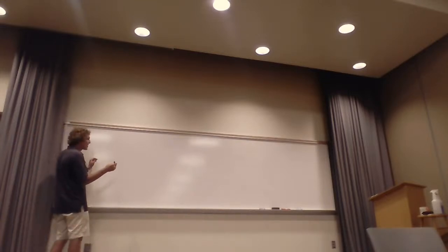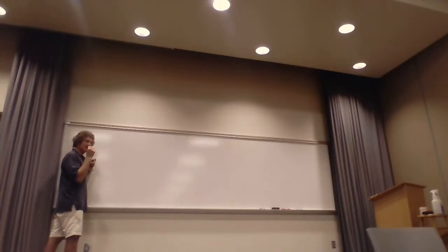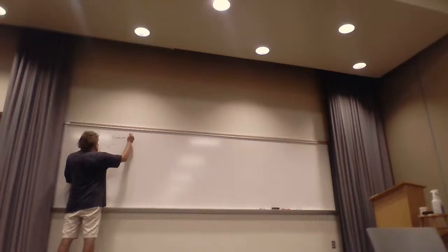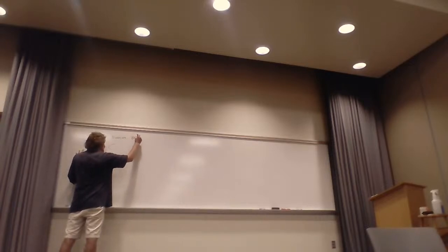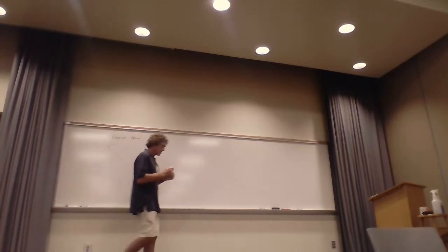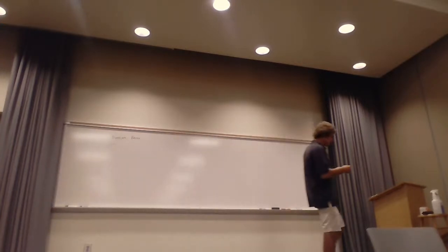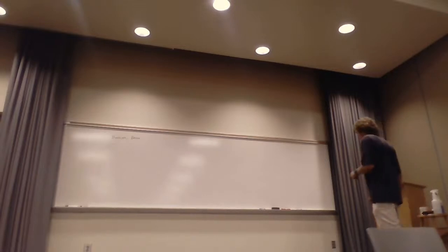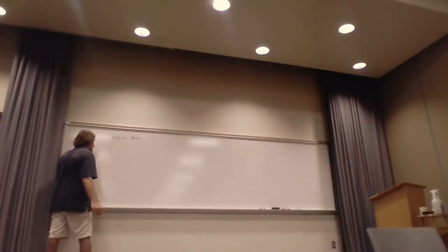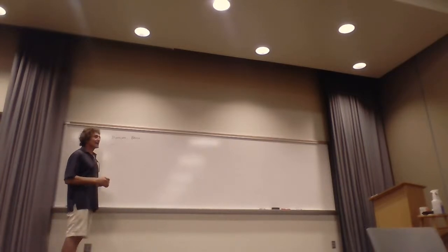So anyway, with radar, one of the things you can do, if you transmit a signal and receive one, you get a Doppler shift. So here's how Doppler works. Does anybody know how Doppler works? I'm going to do the non-relativistic form of Doppler radar. There is a relativistic form of what I'm about to show you, this Doppler frequency shift, but to be frank about it, unless you're talking about astrophysics, there's no real application.